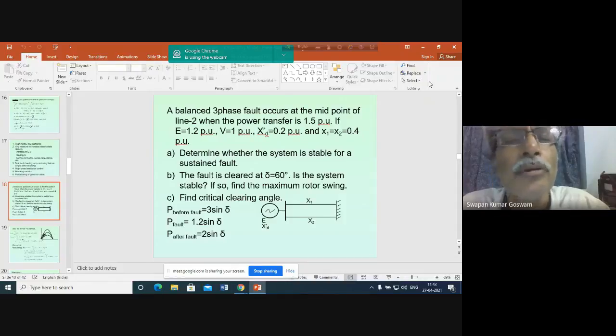During this time, what will be the reactance or the inductance? It is the flux linkage divided by armature current. So armature current is high, and flux linkage is somewhat more than in the subtransient period, but it is actually not the full flux linkage, because there is still opposition from the field winding flux. So if you calculate the inductance, it will be less than the steady state reactance.